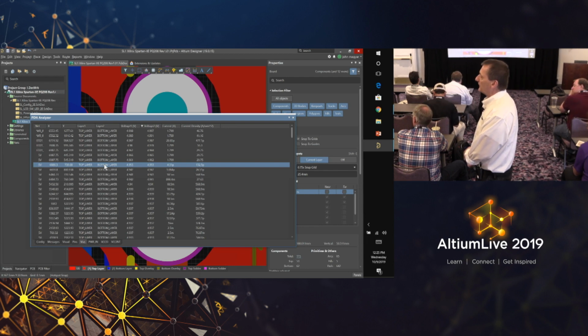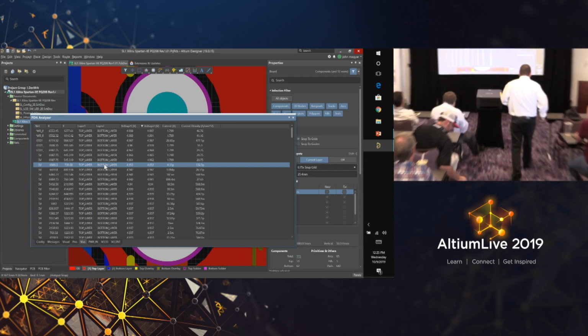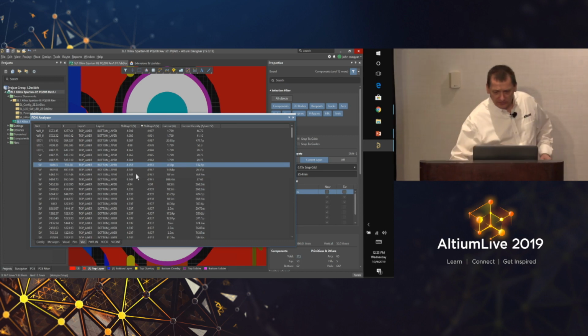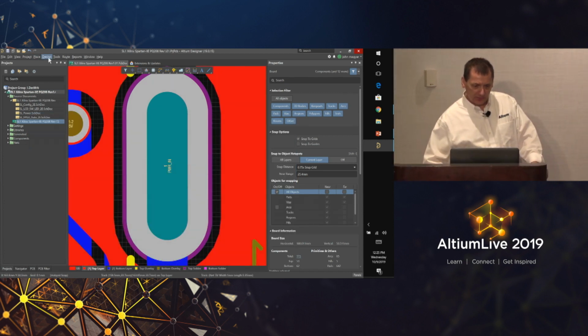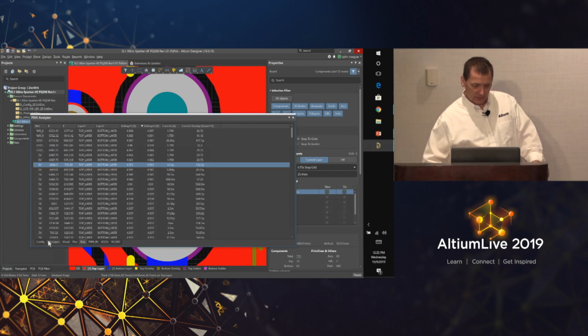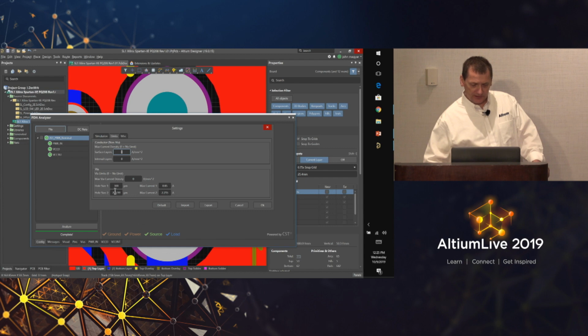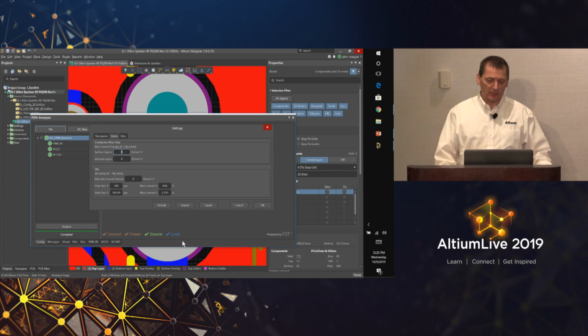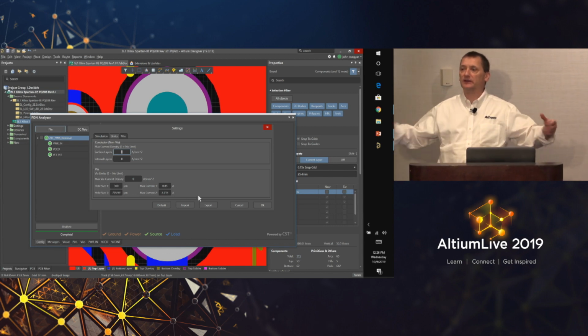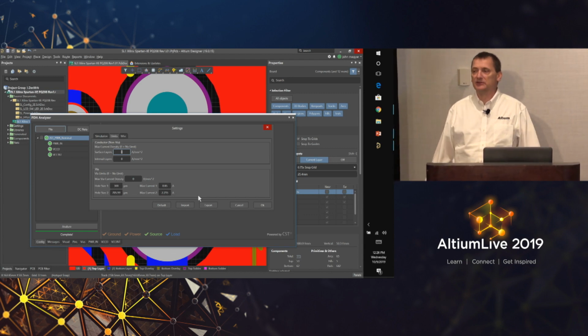So is that in the setup for the simulation then at the beginning? Yeah, I can show you real quick where that is. Let me go back here under Tools. Go back to Configuration, so under Settings and Limits. So here we specify the smallest via used, the largest one used, based on hole size because that has the copper part. And then we did a minimum constraint and a maximum constraint from the smallest to the largest. And no matter what other different types of hole sizes there are, it'll interpolate from those two extremes and figure that out. So that's how you can set constraints for every via size in the design.